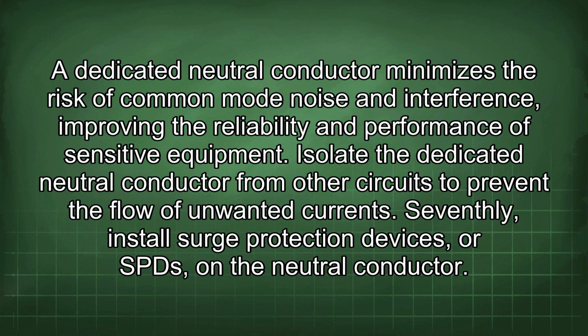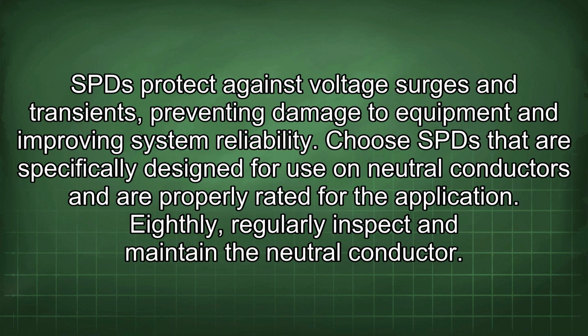Seventhly, install surge protection devices, or SPDs, on the neutral conductor. SPDs protect against voltage surges and transients, preventing damage to equipment and improving system reliability. Choose SPDs that are specifically designed for use on neutral conductors and are properly rated for their application.